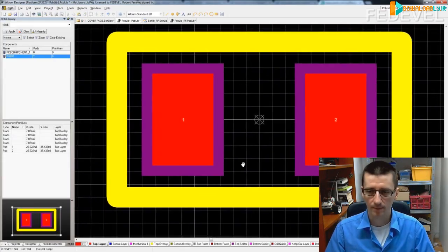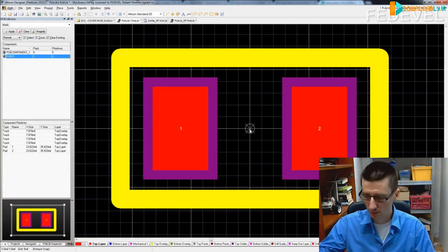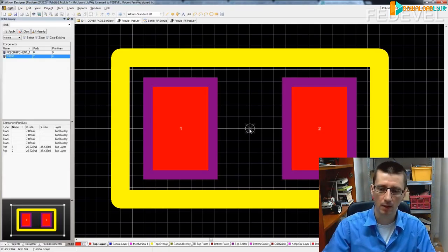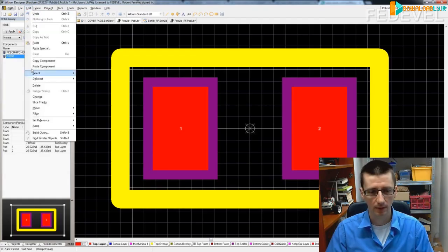A few more things about footprint. There is a reference point which specifies component location when the pick and place file is generated. This file is used by the machine which picks components and places them somewhere. If you have never thought about how this point is used, or maybe didn't even know it is used, for SMT components place it in the middle. You can do it here.